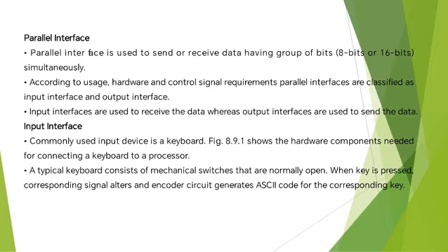Parallel interface. A parallel interface is used to send or receive data having a group of bits simultaneously according to usage, hardware, and control signal requirements. Parallel interfaces are classified as input interface and output interface. Input interface. A commonly used input device is a keyboard. A typical keyboard consists of mechanical switches that are normally open. When a key is pressed, the corresponding signal alters and an encoder circuit generates the ASCII code for the corresponding key.